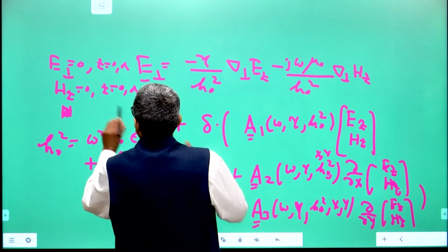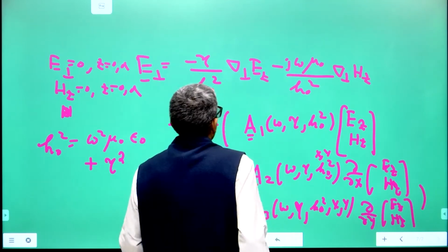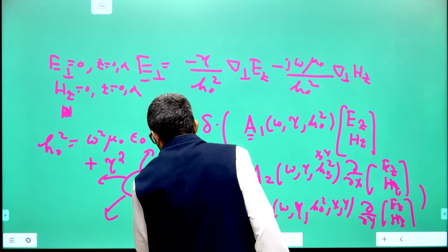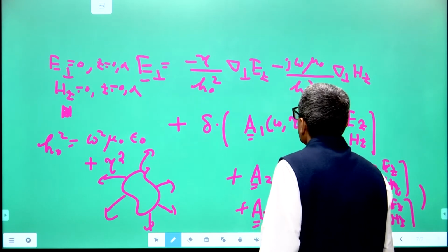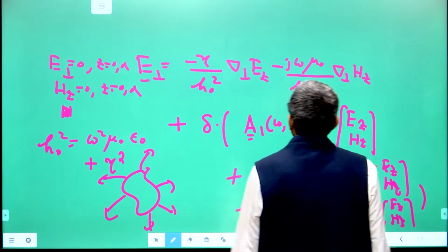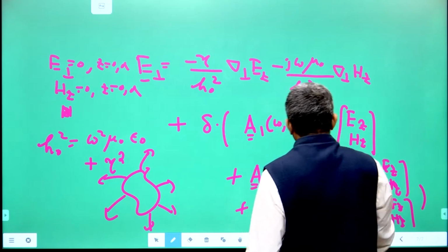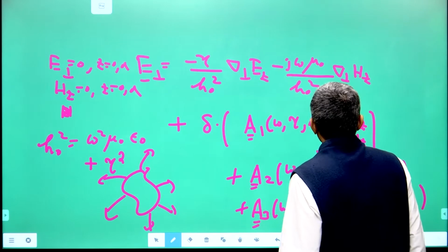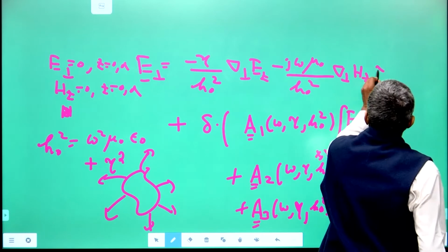That means if you write down the same equation for h perpendicular and take the dot product with n, where n is the unit normal on the outward boundary, and put the condition that Hn is equal to 0 at that point, and use the duality to express h perpendicular in terms of the partial derivatives of Ez Hz with respect to x and y, you will get an equation of the form dou Hz by dou n, dou Ez, it will of course be cross z cap.